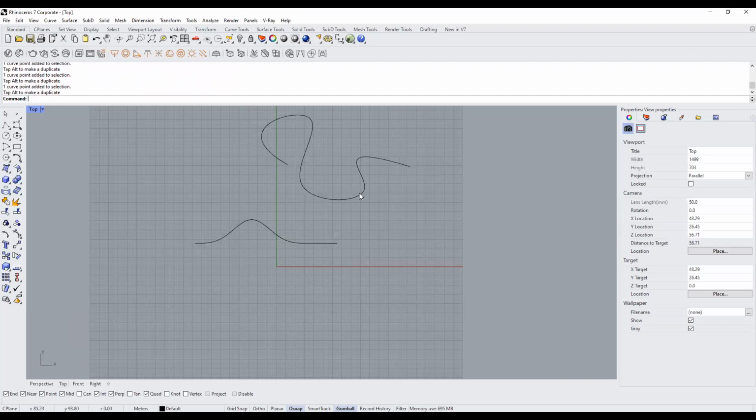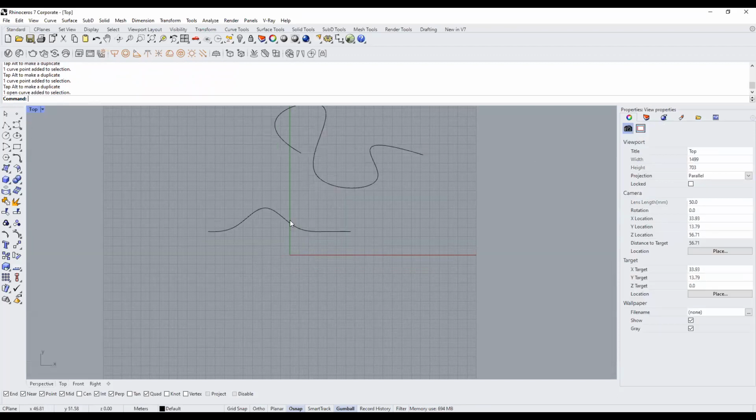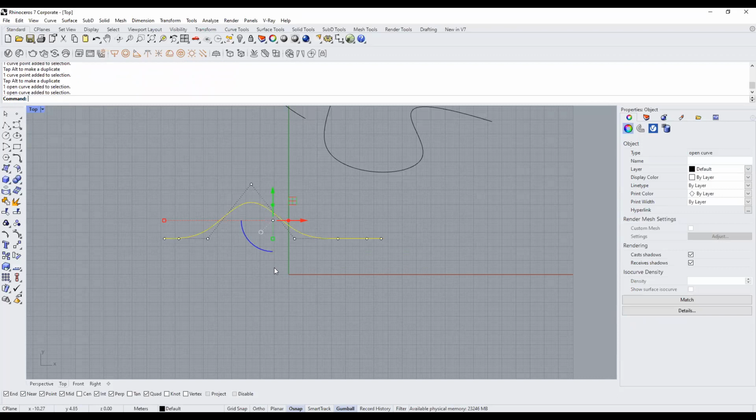All right, so now moving ahead, I'm going to create a few more curves so I can show you how to come up with surfaces out of them. We're going to see a quick technique called lofting, but before we do that, I'm going to create one more curve here. So creating a copy, you can do that in Gumball.